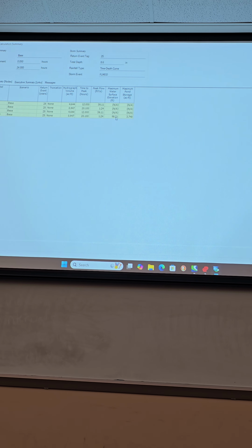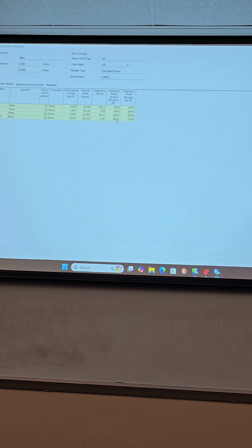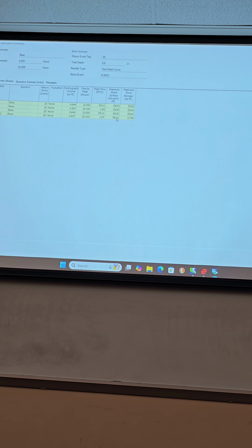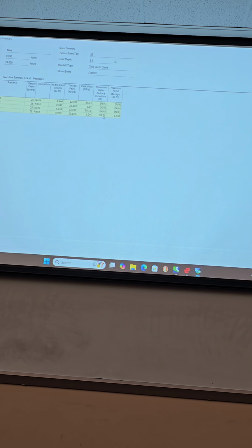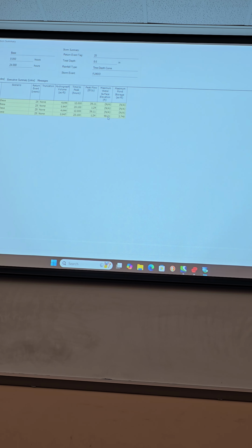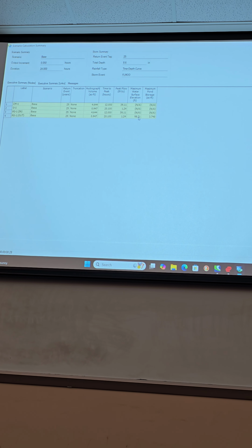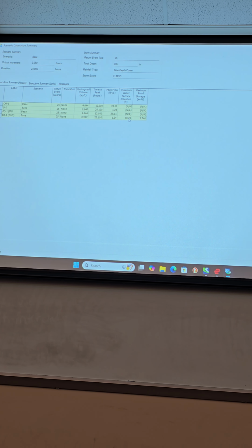Maximum water surface elevation. And what would be a normal flow in and flow out, where you'd say, okay, that's not right? Well, that's a tough question to answer. But what I would tell you is, if your inflow is 100, 200 cubic feet per second, you've probably done something wrong.